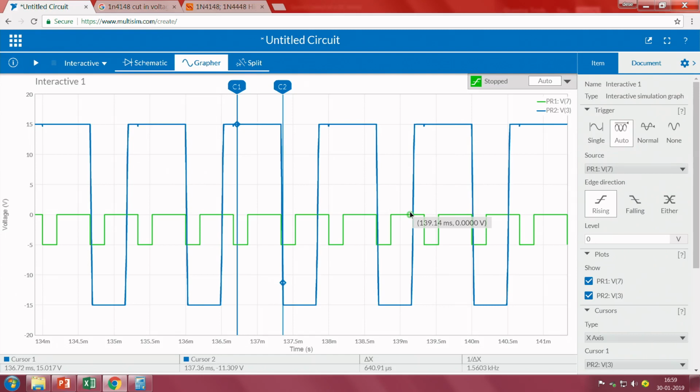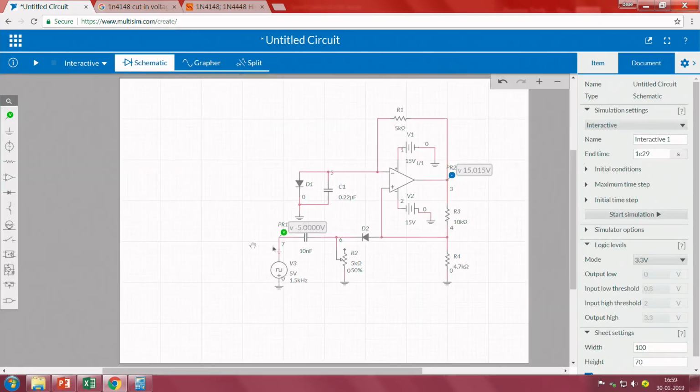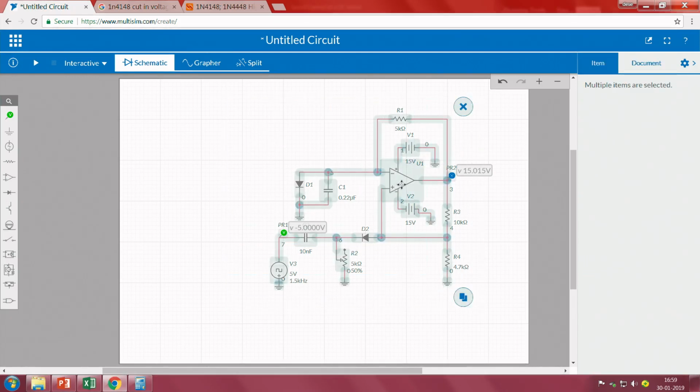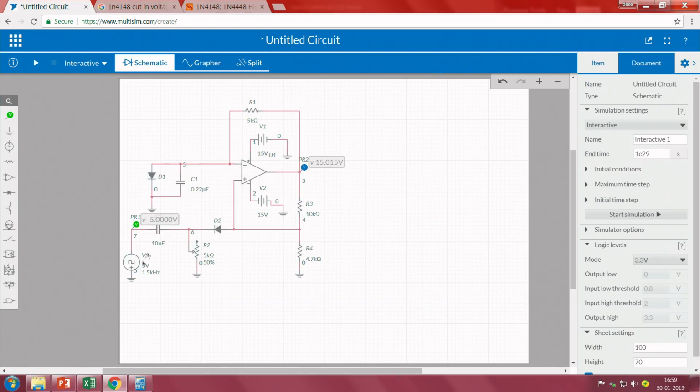So we have followed all the requirements. We have already looked into all the cases. We have optimized the resistance and capacitance values, and we have chosen 3.3 kilo-ohm and 0.22 microfarad, right. So in our case, we are not missing anything. This part is clear to us, so let me keep it aside.